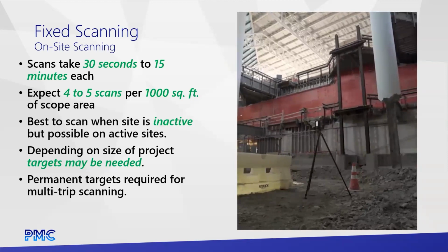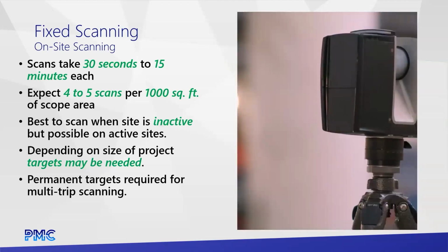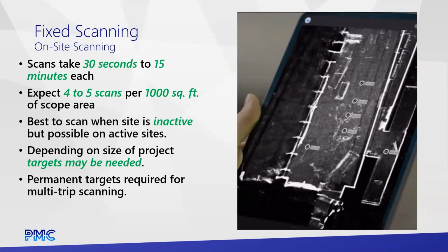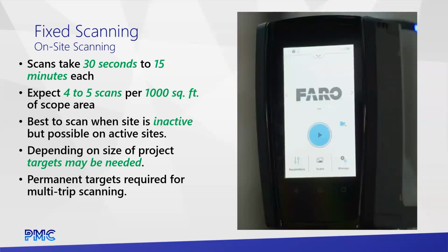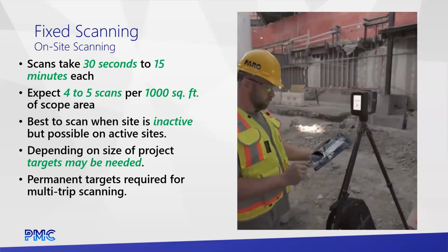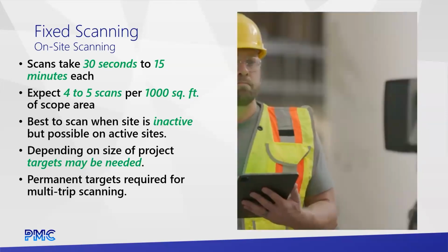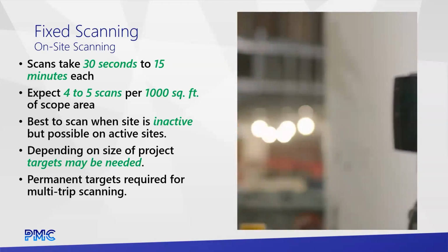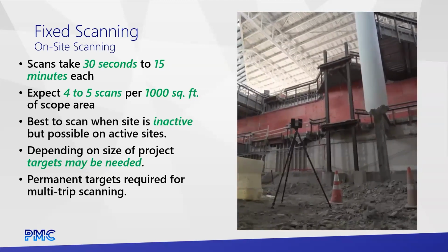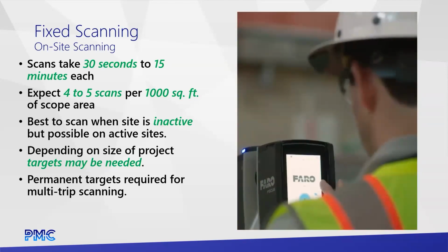And then for some of the more complicated and larger projects, you may want to consider installing permanent benchmarks. These allow for multiple trips to be done and for the data to stitch together perfectly between them. Also, as projects get very large, you're going to need to do traditional land survey to keep the data quality high.